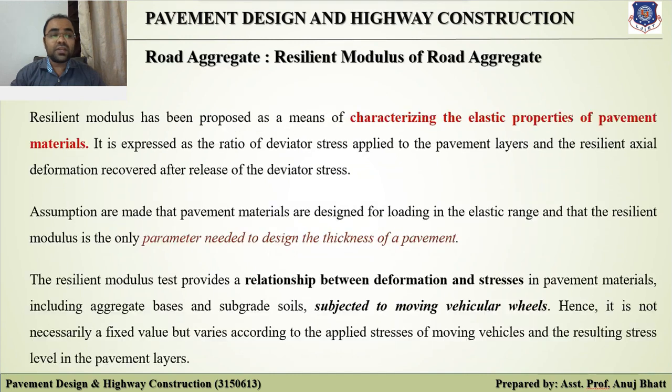The resilient modulus has been proposed as a means of characterizing the elastic properties of pavement material. It is expressed as the ratio of deviator stress applied to the pavement layer and the resilient axial deformation, that is, the strain recovered after release of the deviator stress.